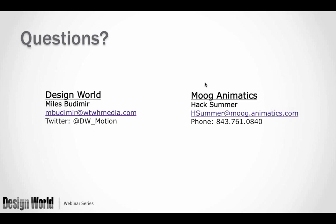Well, honestly, it's a catch-22 on our product because our product contains a drive and the controller, so it contains the circuit boards. And some people say, well, I bought a motor, the motor's sealed, I'm ready to go. Well, when they buy ours and it's sealed and it's ready to go, it's actually the controller and drive. What they may not think about is, I want to buy this motor and put it on, say, a pan and tilt outside of an airplane or a helicopter. Oh, wait a minute, I need the drive and controls to penetrate the hull internal to the pressure barrier. Well, now you have all these cables that have to go through that pressure barrier. Your cost of penetration into that area goes up. With our product, the only thing you have to get out there is communications and power. That's it. So it actually lowers your system cost. If you have, like I said, a pan and tilt, that's at least 2 axes.